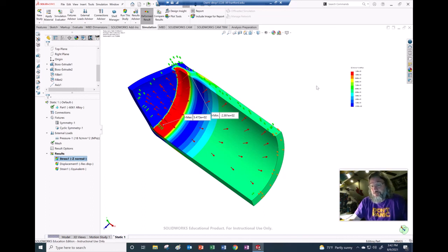And you'll notice as an example, I just went ahead and threw a bunch of stuff in there, and I got wrong answers because I didn't model it correctly. So you have to be careful with these simulation tools that you can just throw something up against the wall, get a result, and it not be a correct result, a lot of times because you didn't put the boundary conditions in the right way.